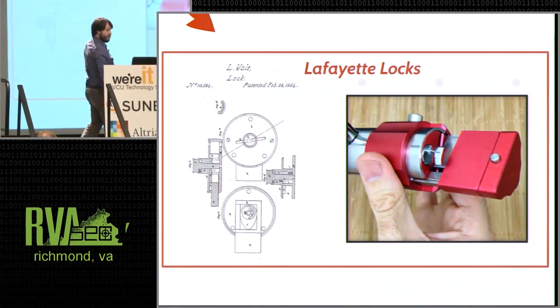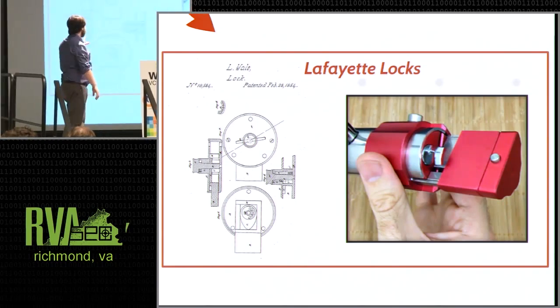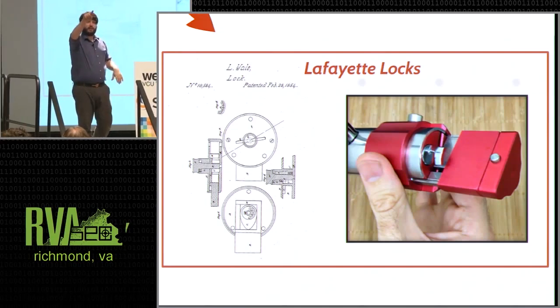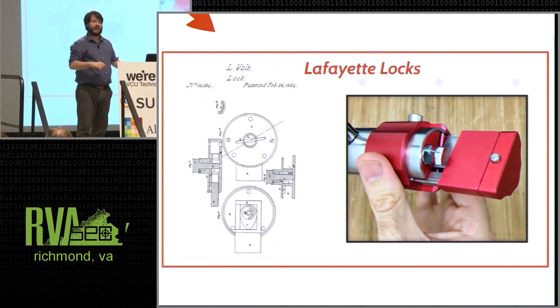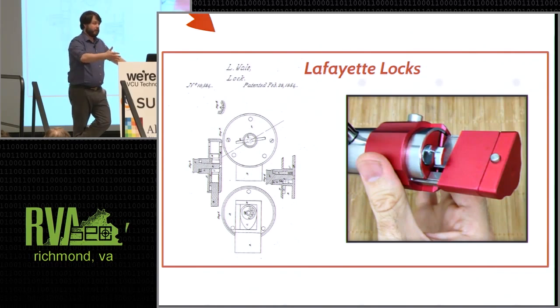This is Linus Yale Sr. in 1854 on the left, and he's devised a key, which you'll actually see in the top left, that little bean-shaped thing with the little holes in it. That's actually the key. The key would be inserted into the lock, and then a panel turned without you touching the key. The key would travel to where the tumblers were. It would act on the tumblers. The bolt would be thrown open, and then the key would be returned to you. Like a bad quarter moving through a vending machine, it would pop right out again.